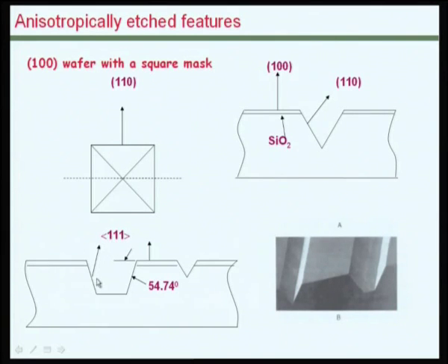Hence, as the etching process continues, this plane gets defined and the etch floor would go down, but the side walls would not remain vertical or inward curved, rather it would remain as a continuation of the 111 plane starting from the etch window opening. This obviously is particular about the 100 wafer.